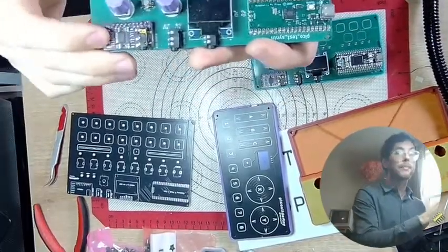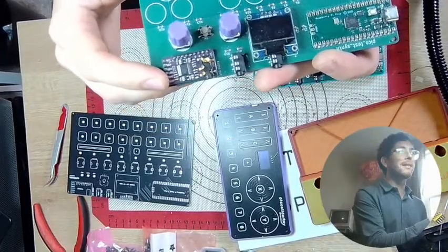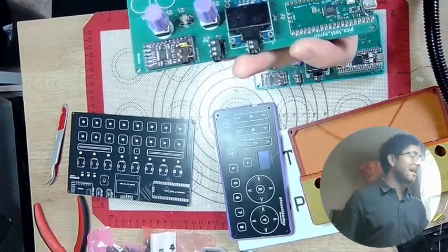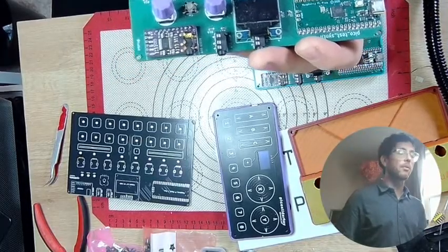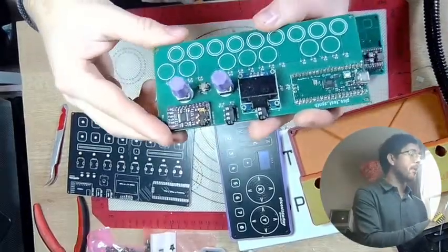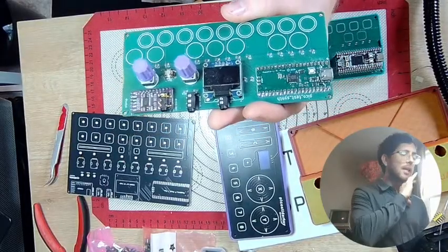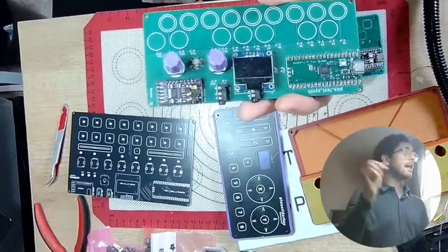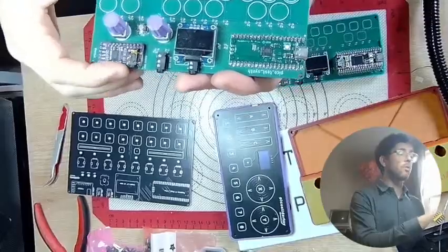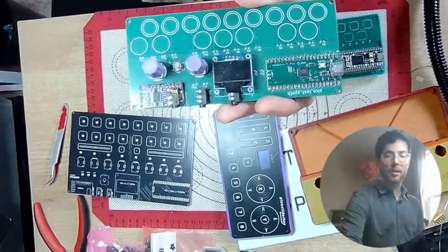You'll notice this guy, which you'll see a lot. I don't know if I got it centered up right. It's the PCM5102, a classic, cheap Amazon DAC. I've found the components are actually kind of hard to find sometimes when using them on your own projects. But it's pretty cool. I don't think it needs any configuration. You just have to give it a valid I2S signal, and it'll automatically pick up the sample rate, etc. So it's really easy to work with, and it provides line output, but you can actually use headphones with it too.